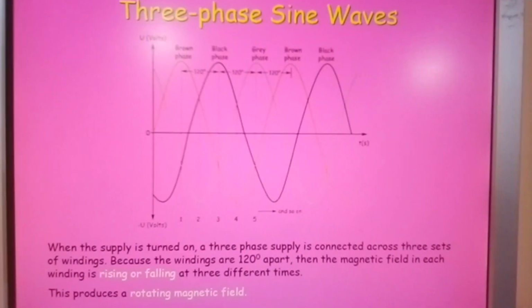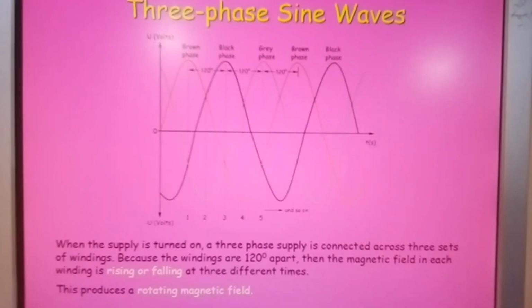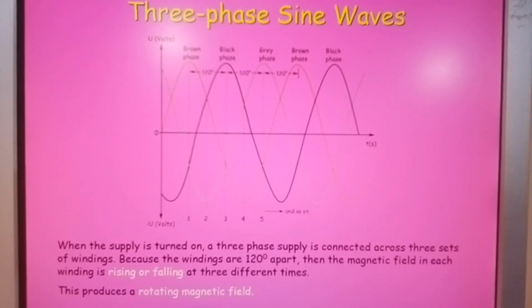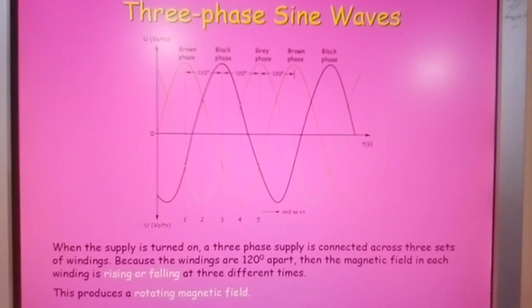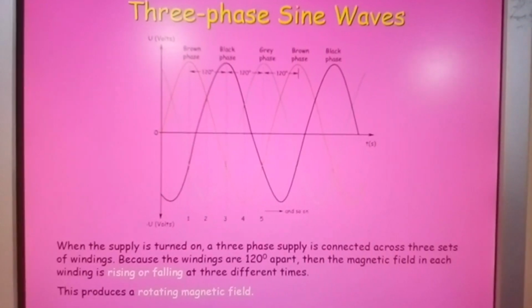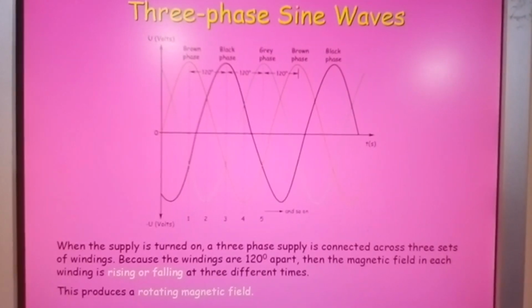But if you were dealing with your domestic lighting, for instance, then yes, your light actually will be going on and off 50 cycles per second. But because it's doing 50 cycles per second, you're not able to see that switching on and off. But if you slow it down, you can. That's what you would then call strobing.